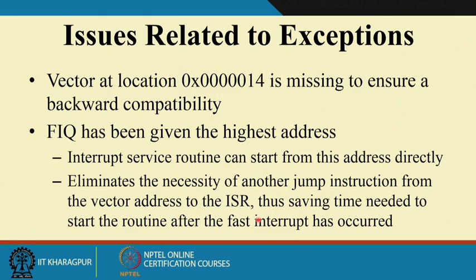For other exceptions, what we have to do is put a jump instruction. So, every ISR code for those exceptions has an overhead of one extra jump instruction. That way it will take some more time for activation compared to the FIQ interrupts. So, we can see that the FIQ interrupts are faster in the ARM processor because of